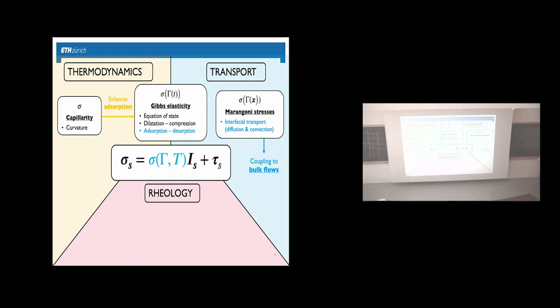So the thing is, the liquid gets pulled up by the surface tension until there's a length scale of about 2 millimeter, the gravitational length scale, and you get the tears of wine that are about 2 millimeter in size, right? And this is because I get a coupling between the surface flows and the bulk flows. I create a surface concentration gradient by a bulk flow. And this is something we'll have to worry about when we do experiments.